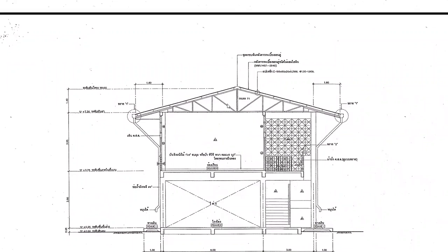It's just a drawing that doesn't mean anything, because this is not a structural drawing. People are not going to build a truss based on this picture. It is your job to set up the purlins on the joints. And now you know that the spacing is going to be two here, because you cannot have one because of the slope.